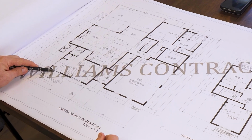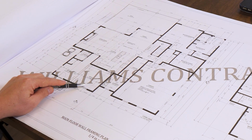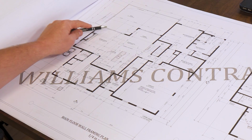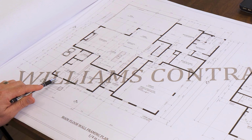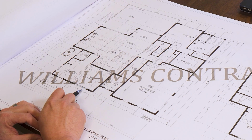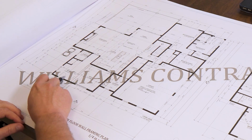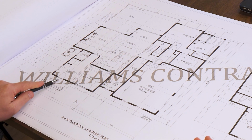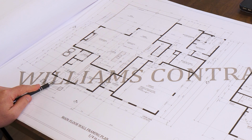We've got the front door size called out. We've got the front window sizes called out. This is typical around the home for all the exterior openings. You can see our dimensions are called out on center. One of the great things about calling out on center is if you change, say the size of the door goes from a 3-foot door, maybe you want to oversize to a 3.6, that center line typically is going to stay in the same location.